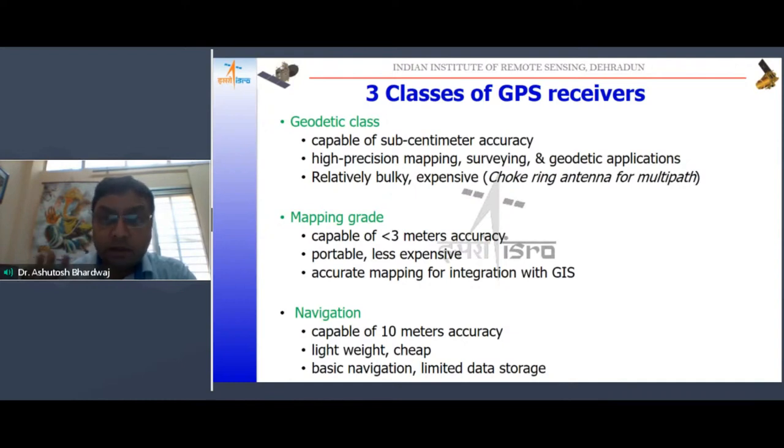coordinate conversion and all. Similarly, Leica is providing a smart station. So in a smart station, you have a total station along with a GPS receiver. So there also you have a reflector, 360-degree reflector is there. So using 360-degree reflector in such difficult areas, you can again calculate the coordinates inside the tunnel or in other difficult situations also.